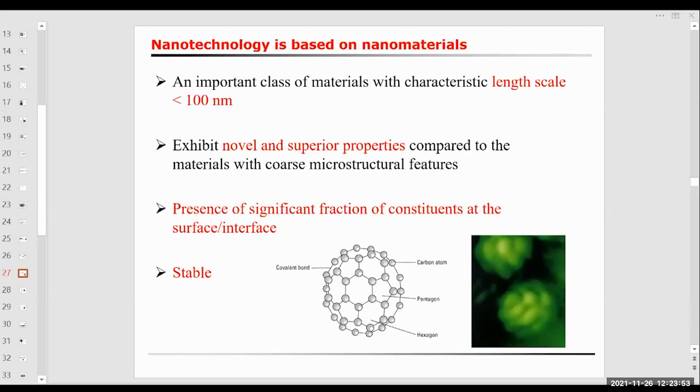These are the constituents. But within a crystalline particle, if you carefully observe under a micrograph, there will be small entities, small volumes of material, called sub-constituents or sub-entities or sub-volumes of materials. Within each such entity, the atoms are systematically arranged, but in a different manner. One crystallite will be oriented in one manner, another crystallite in another manner, but all of these crystallites are adjacent to each other, and they constitute a particle. That is the difference between particle and crystallite.